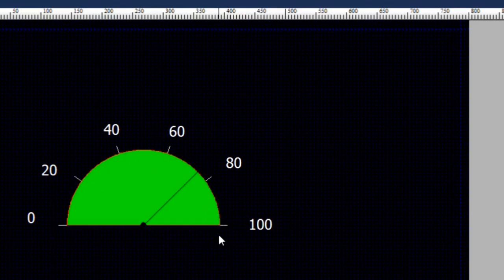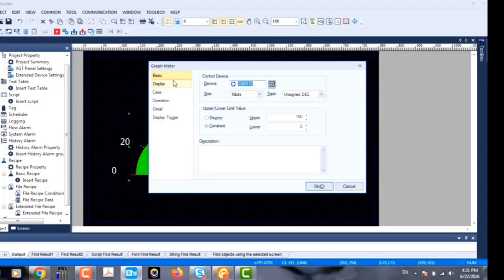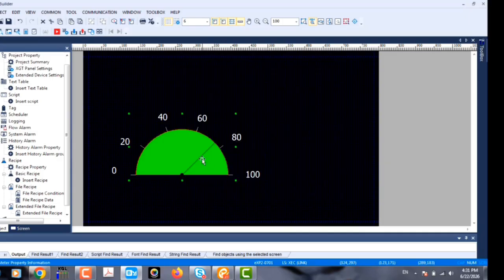Now, for the purpose of testing this specific chart, when we connect this HMI to a device like a PLC, we need to remember that we previously set the internal device address to MW10. It reads this MW10 from the PLC, and based on the changes inside it, this needle here moves.